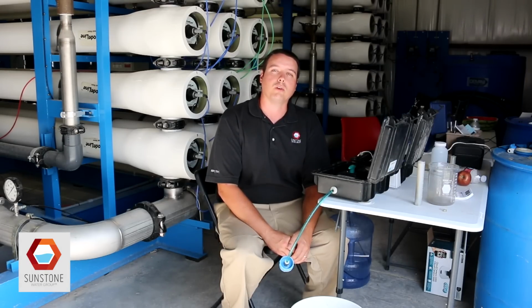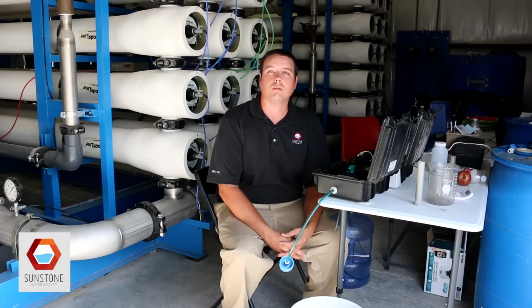Cleaning will need to be done very frequently. SDI in the range of 3 to 5 will pass through an RO system for a little while, but it will also require frequent chemical cleanings. When we get down below 3, water actually can run through an RO system for quite a long time in between required cleanings, but it will still require periodic maintenance. And then an SDI of less than 1 indicates that water has a very low tendency to foul in an RO or other membrane type of system.